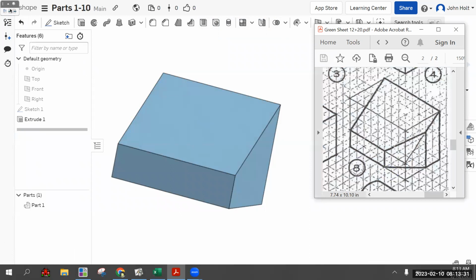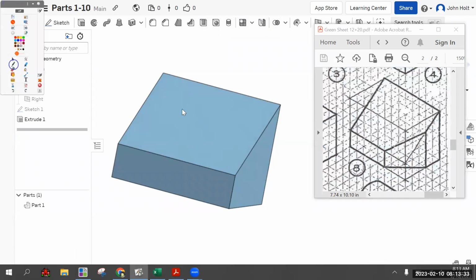So if we make a sketch on the bottom that is this shape, we can then cut extrude up and cut extrude all of it. And this shape from this front corner is 3 in from either direction and then connect.